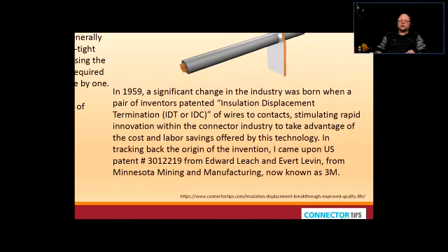Like for example, when we are doing our infrastructure cabling or wiring, you can do this, no problem, because there is a termination there and it's nice and steady. There's no vibrations involved, like for example in machinery, like some sort of electric motors running and sending the vibrations through the chassis that could wiggle the connection out of the connector, all right? Then in a car as well, right? So in a car, you would have either soldered or crimped type of connections. Mostly would be crimping connections in the car industry, right? However, in the cable infrastructure, when there is a steady building, there's no huge vibrations, right? Well, if a train goes by not too far from there, that's not considered a huge vibration, right?